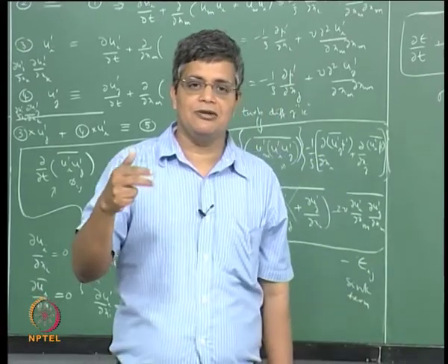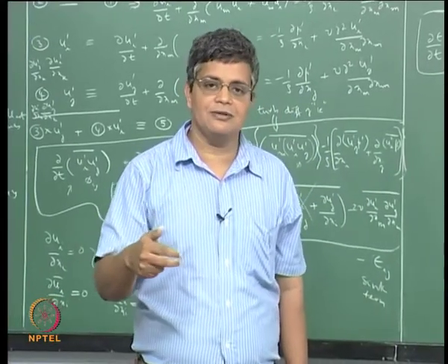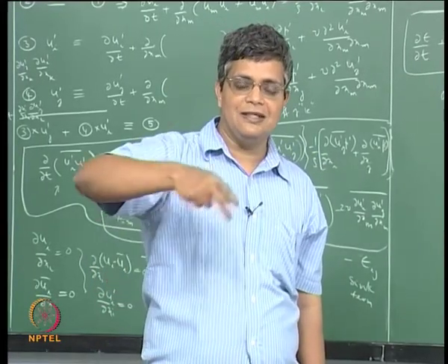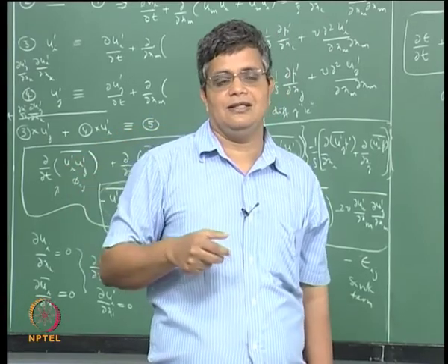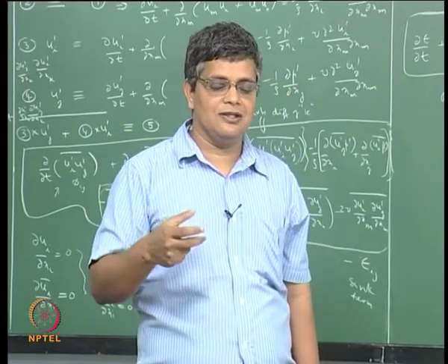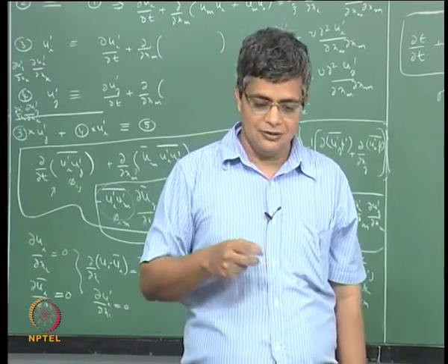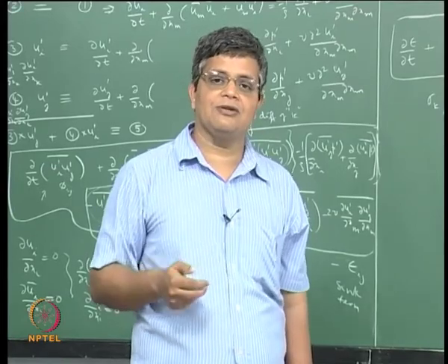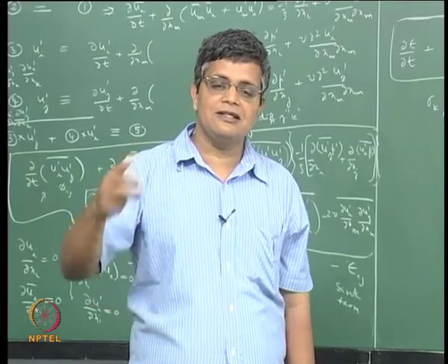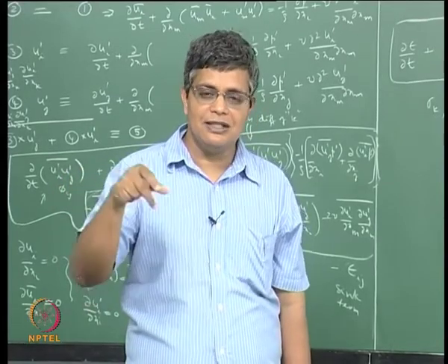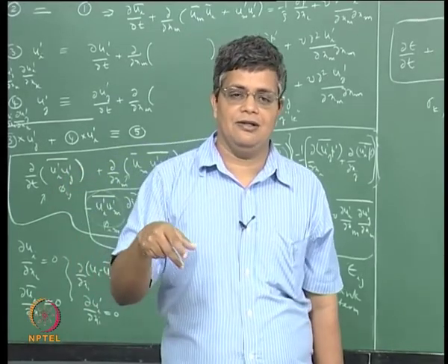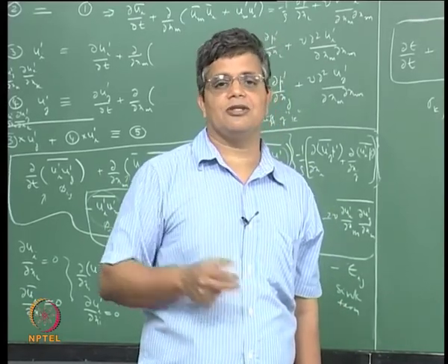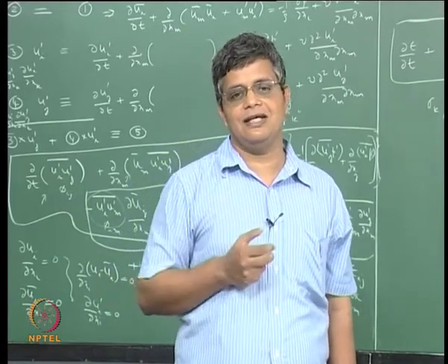So the rate of this mixing and the rate of this effective flux that is generated is determined essentially by the intensity of turbulence, which is causing the eddies to be present, and also the size range of eddies that are present. So in that sense the mixing of K and epsilon, these different scalar quantities, is not governed by the intrinsic property of the K and epsilon, but it is governed by the rate of mixing, and it is the size of the eddies that are present.